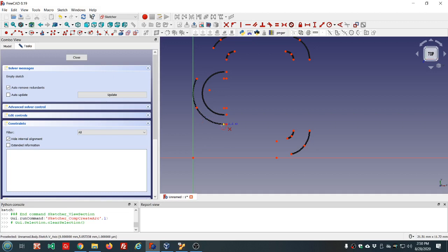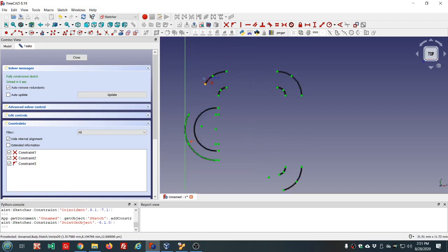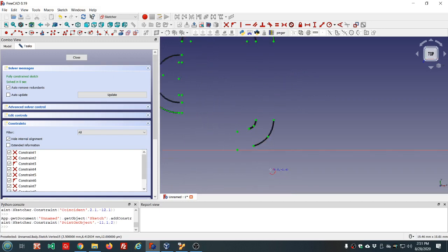You select first the two outer points and then the inner point. And as long as you're getting your coincident constraints, it'll all be fully constrained. If you get to a point where you're seeing white instead of lime colored edges, it means you missed one of those constraints.